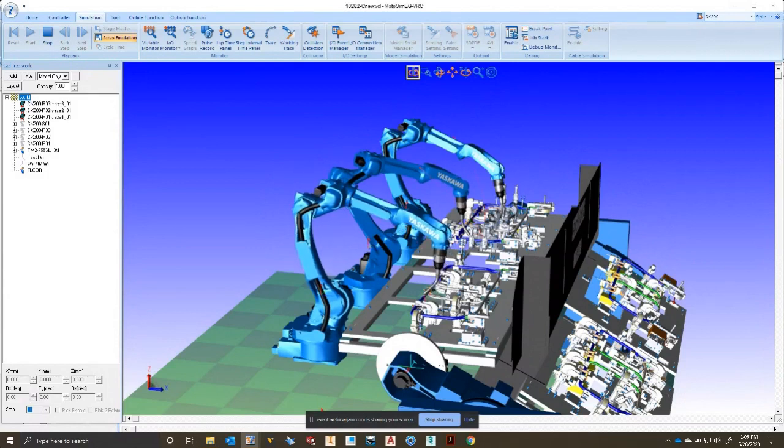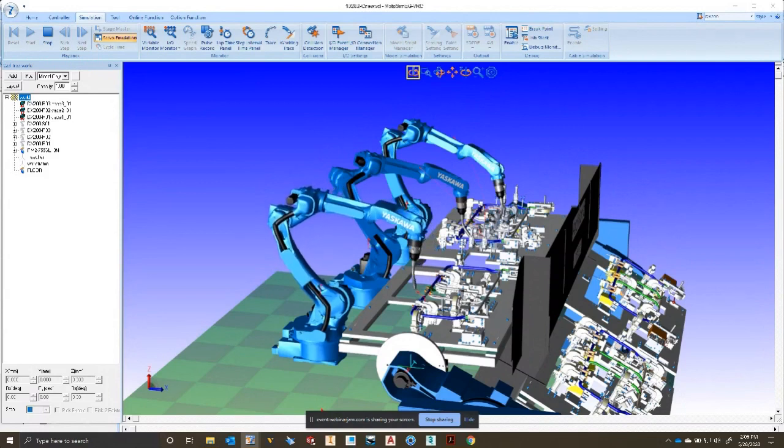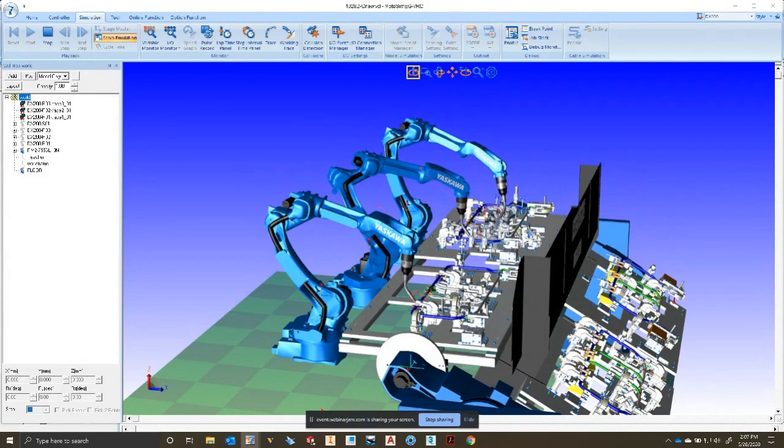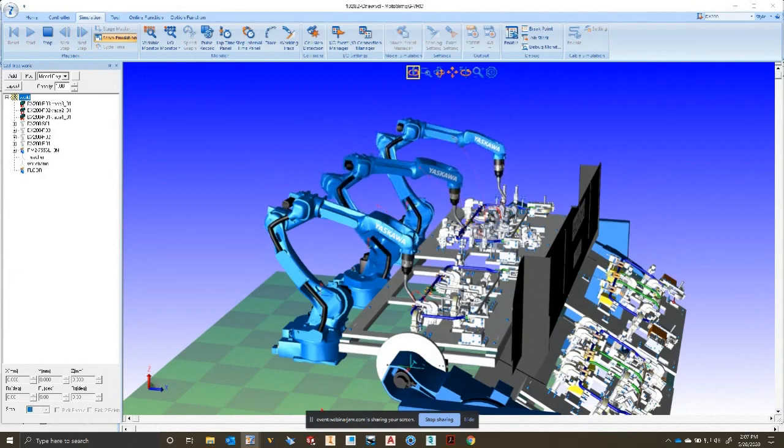The other area would be, let's say you are running a part. This is probably more common, actually. Your part A is being worked on all day long, and you need to program part B. Well, program part B in the simulation, save the files out, and put them into the real controller. When you're ready to run, do that run for part B. And that's also quite common.